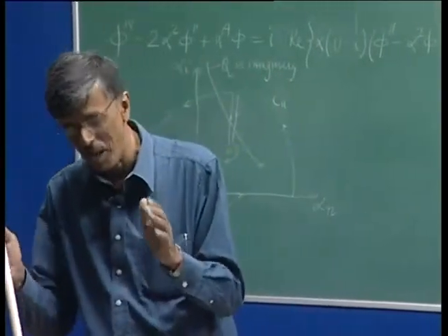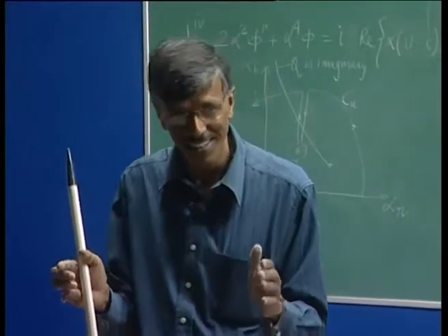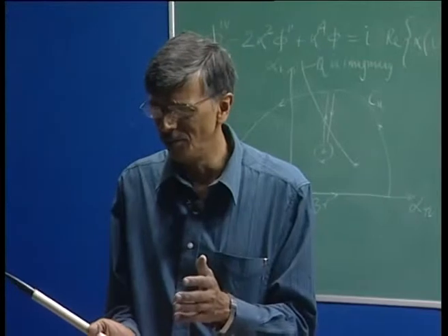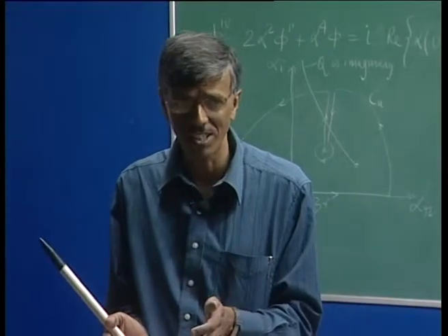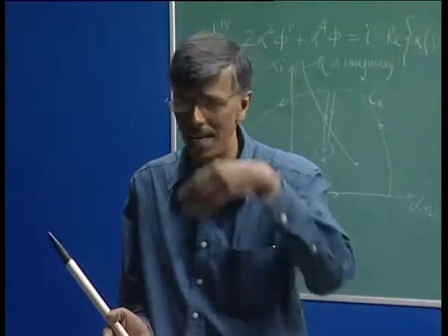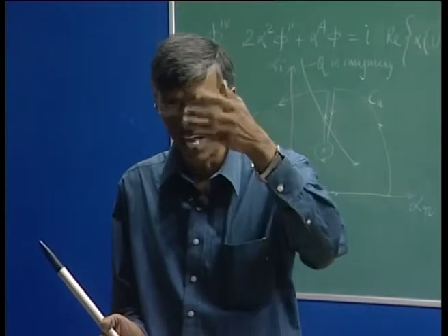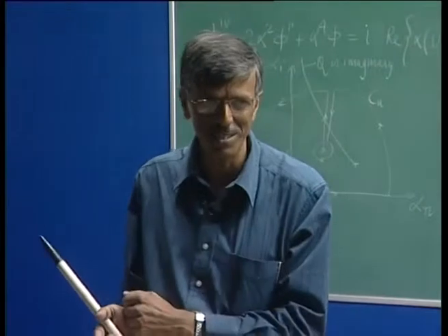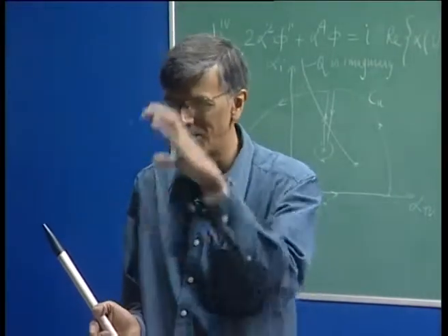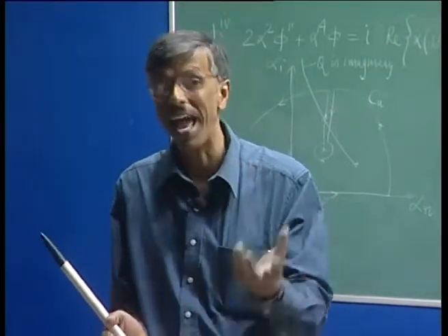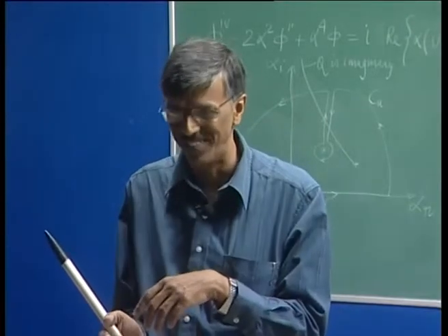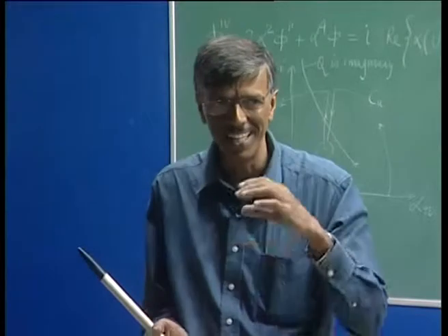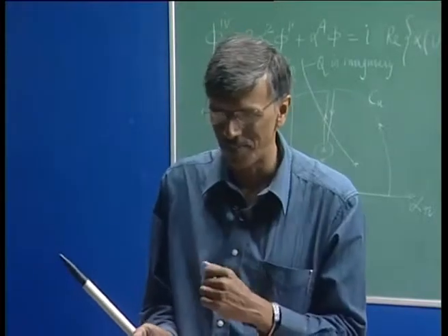Now, sum it up for me. What are we looking at? We have a real flow which has a singular structure in terms of boundary layer and a potential flow. Then within this boundary layer, what have we done? We have created some disturbance, and within this boundary layer, now we are talking about another singular perturbation problem. Okay? So, within the shear layer, I have an inner layer and an outer layer.